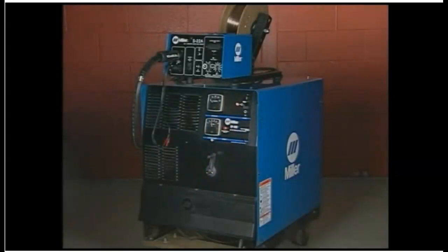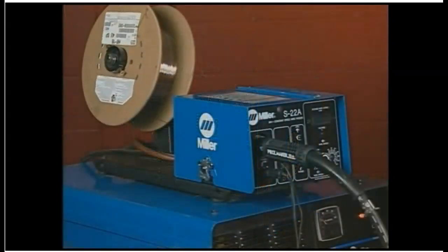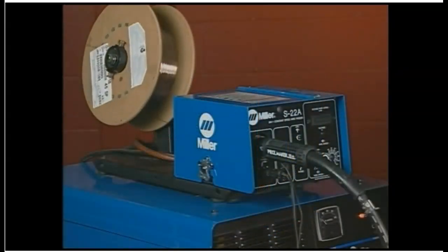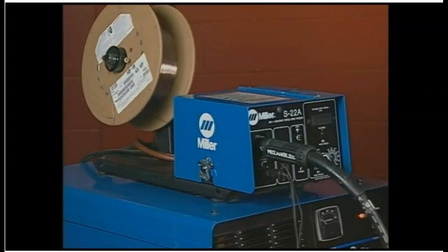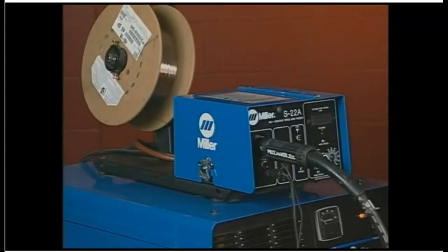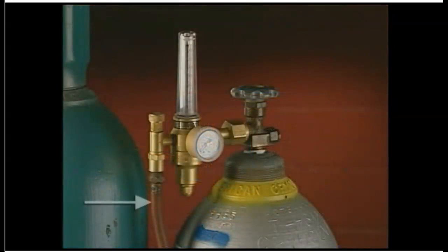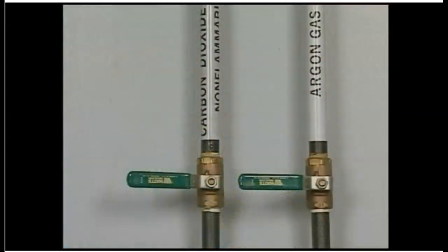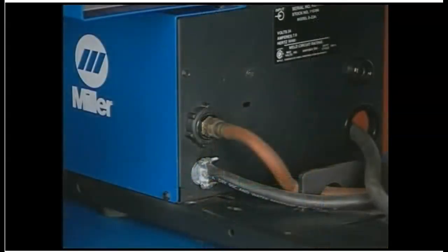form the weld. The gas metal arc process uses a power source to supply welding amperage and voltage for the welding arc. A wire feed unit, typically powered by a line from the power source, supplies the electrode wire to the weld. A gas hose carries shielding gas from gas bottles or from a gas manifold system to the wire feeder.